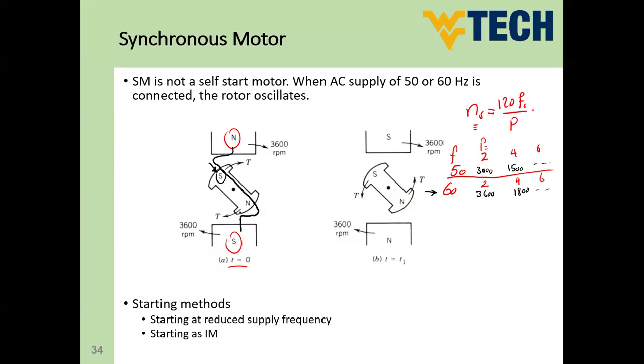So this is the flux path. And you know that a feature of any flux line is that it tends to reduce its length. So it will attract this pole in order to be in front of the N exactly here, giving the minimum path.